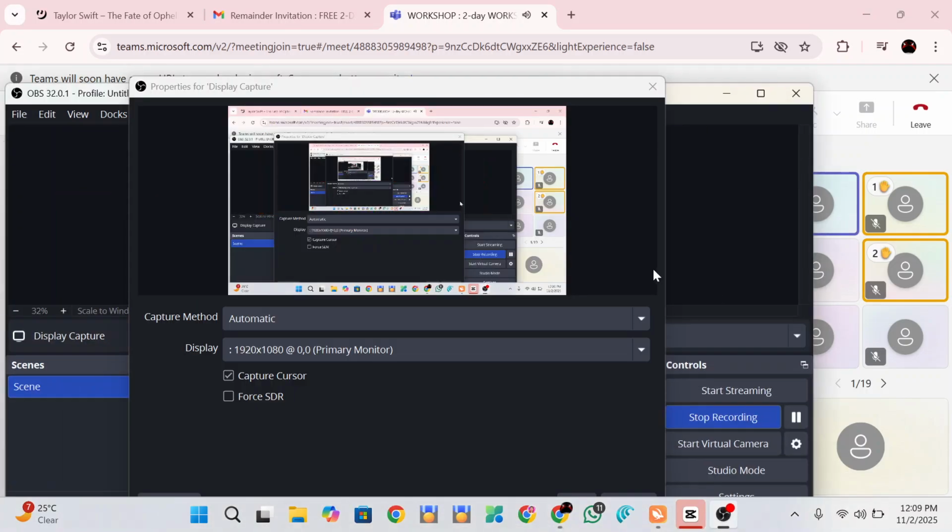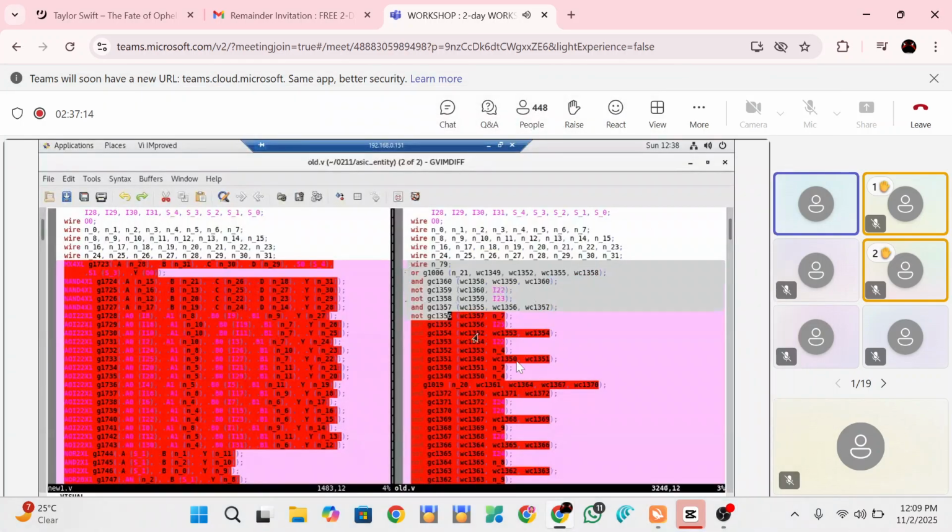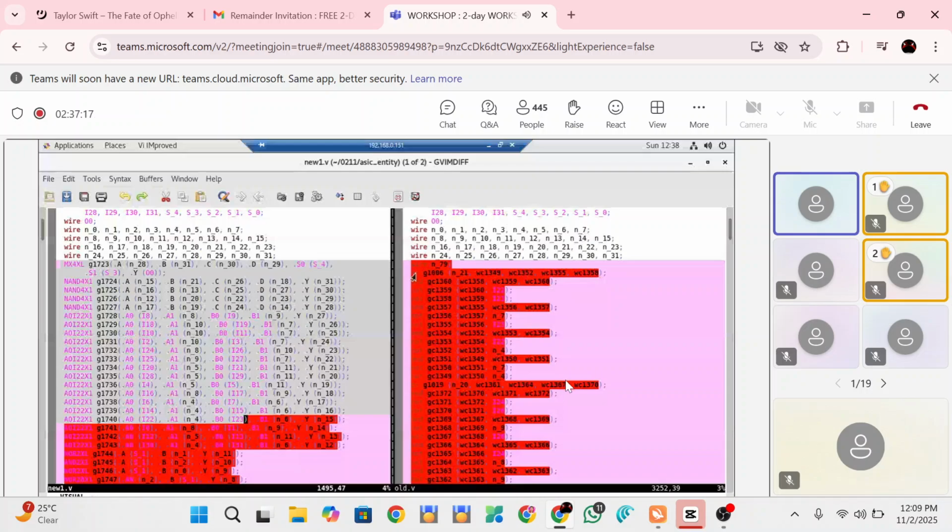You can see there is a NAND gate of some cell. But if you see here, there's a real character of NAND gate for this. But there are two different cells. I'm just giving an example, this is a real character assigned from the technology. This character will have a layout, the structure from the LEF file. The LEF file has a map of that when it is properly placed on the physical design, on the die. So that is how the mapping will be done.